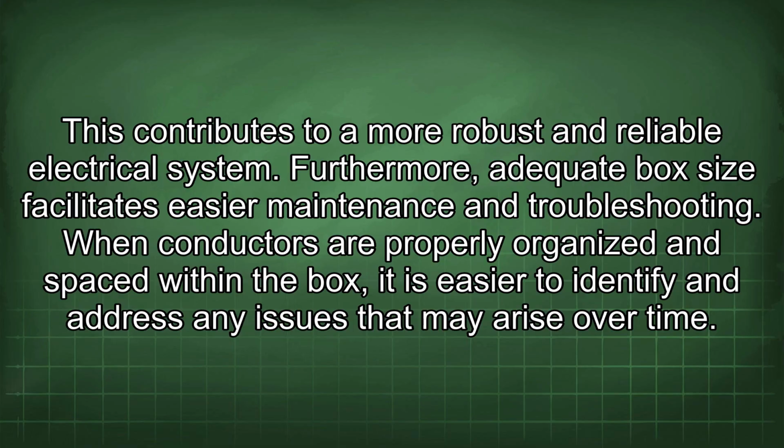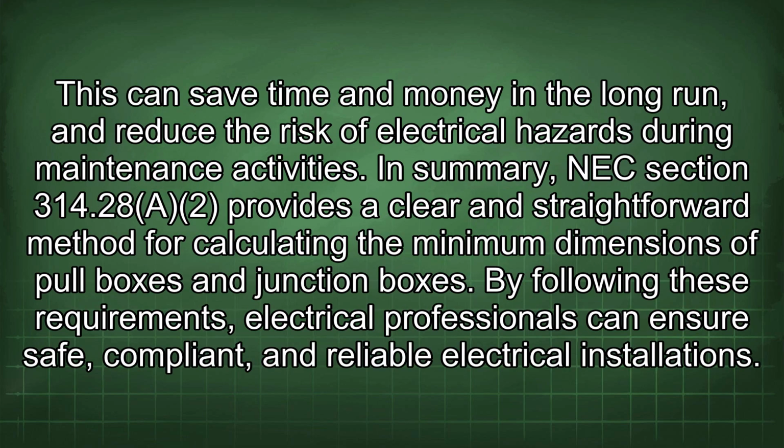Furthermore, adequate box size facilitates ease of maintenance and troubleshooting. When conductors are properly organized and spaced within the box, it is easier to identify and address any issues that may arise over time. This can save time and money in the long run and reduce the risk of electrical hazards during maintenance activities.